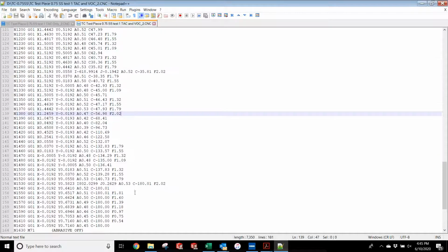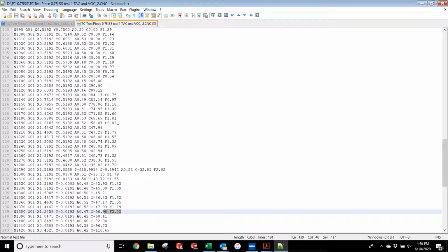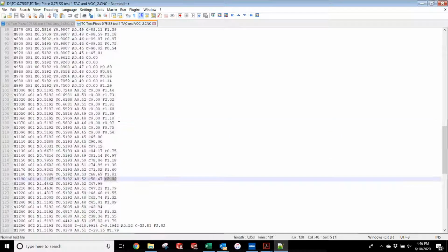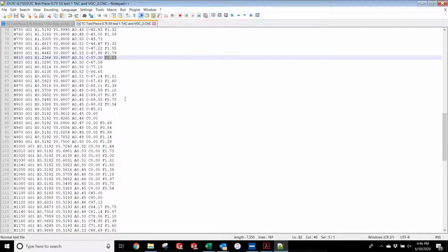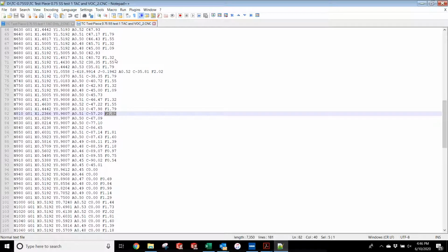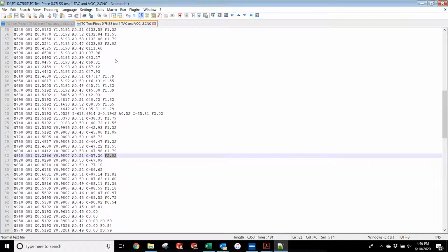So it looks like on this one you might have reset the quality because the maximum that we see in here is all 2.02, which means it should cut quite nicely. So the fact you had to hit it out could have been an abrasive flow issue. I think I must have changed that after I cut that part. I don't know. Maybe not. Because one side is definitely substantially rougher than the other.